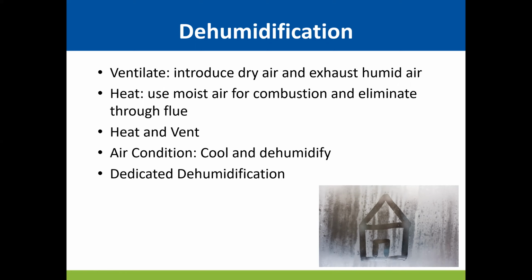And what we're doing is we're introducing dry air from the outside and exhausting humid air from the inside. Okay, we're exchanging air. We can heat, okay? Now, heating actually, if we just heat, let's say we just use hydronic heating with bench heating, then all we're doing is we're raising the temperature and lowering the relative humidity and vapor pressure deficit, but we're not actually removing any moisture, okay?